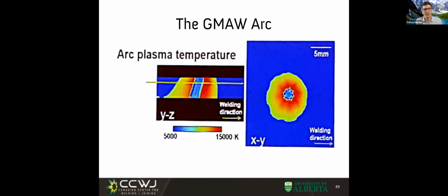But it's not argon. Right here at the core, we have the metal vapors. And these metal vapors ionize much easier because metals conduct electricity already. They don't need to be vaporized to conduct it. So the generation of heat is much lower here. And then the amount of metal vapors is lower on the sides, and the arc then has all the proper resistance, and it gets very hot. Very different in MIG arc than a TIG arc because of these core of metal vapors.